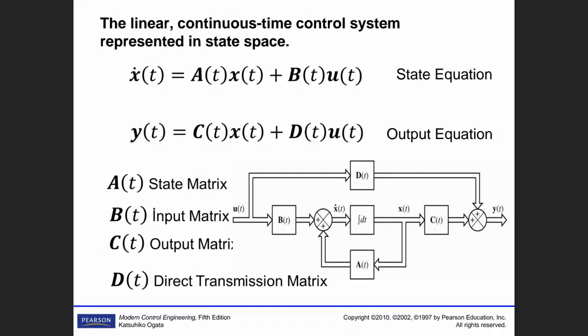The basics of the state space method, listen carefully, is such that we write the equations in time domain. This is the first point you should not forget. The second one, we get rid of the second derivative. There's no second derivative here. So what we defined as the x1 and x2, then x1 dot and x2 dot.